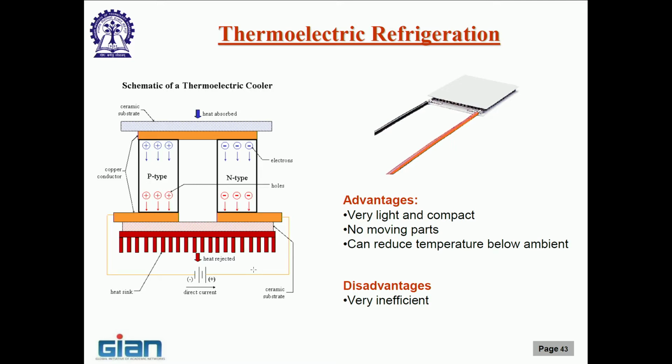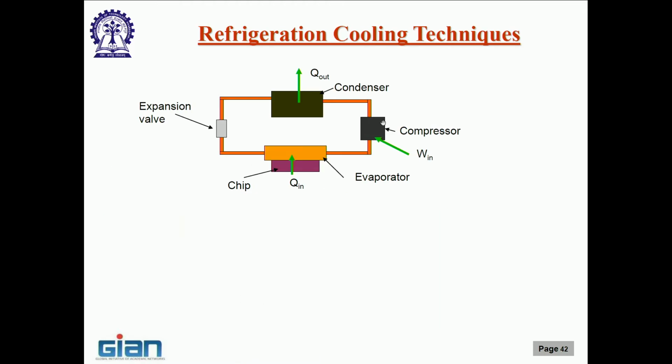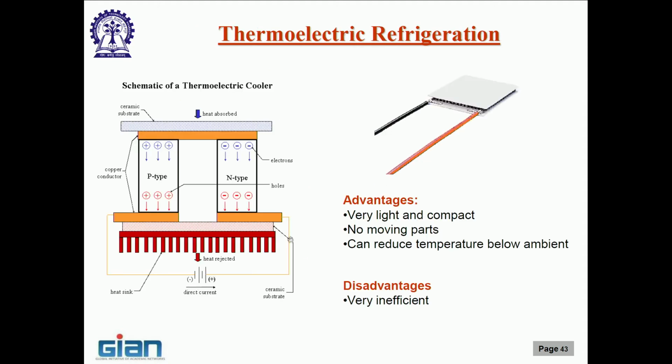Okay. How is this possible? How can I draw a parallel with a regular refrigeration system? Yes, the heat is flowing definitely, but where is the work? I have a compressor here. What is doing the work here? That is the thermoelectric effect. The energy that I am applying externally is electrical energy, compared to mechanical energy in a compressor. Of course, the compressor also needs electricity to run, but finally the work input is mechanical work, whether it is a reciprocating compressor or a centrifugal compressor, whereas here the input energy is electrical energy.